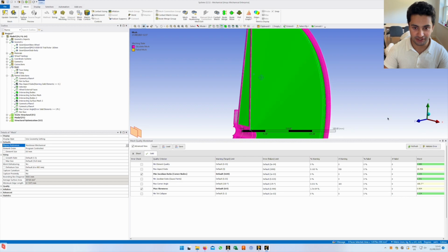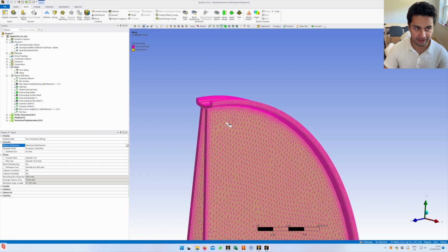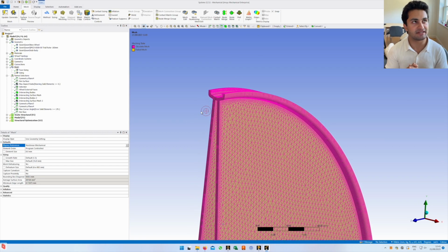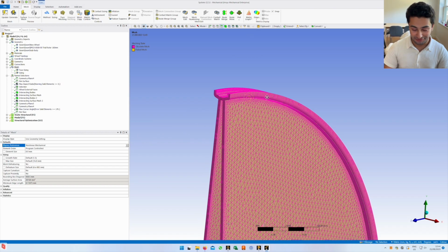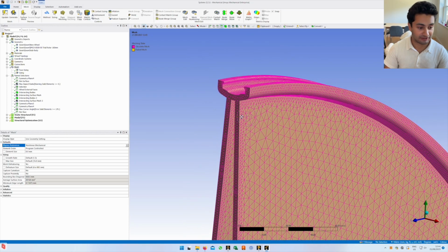However, Ansys advises that for thin-walled models, where the thickness is less than 10% of the area in the other plane, then you have a non-linear model where Ansys should be calculating the deformation after each load increment. So that was probably a lot to wrap your head around, and clearly I've not even wrapped my head around it fully because I could barely explain that.